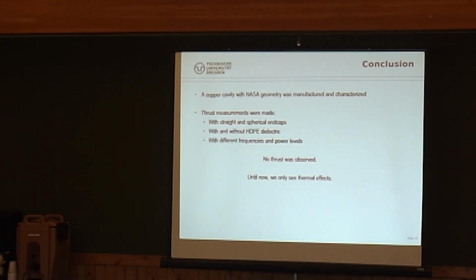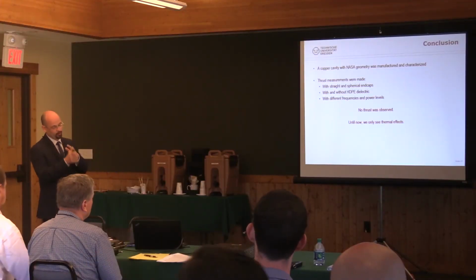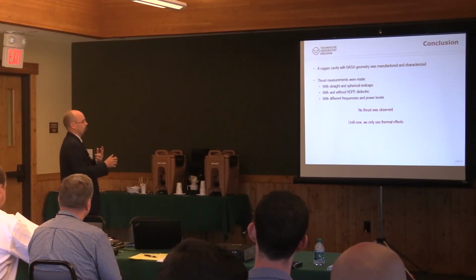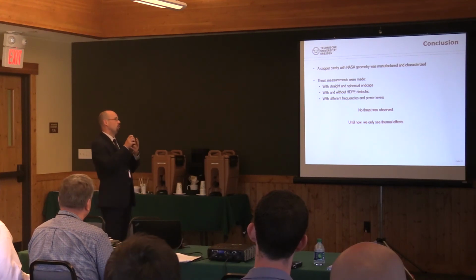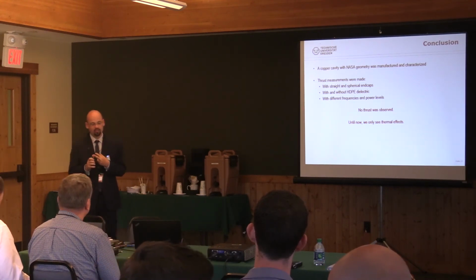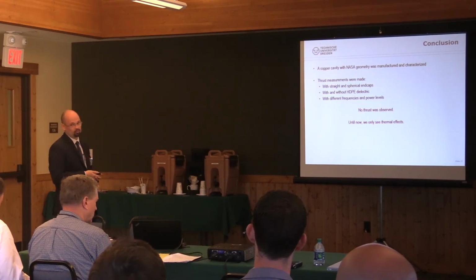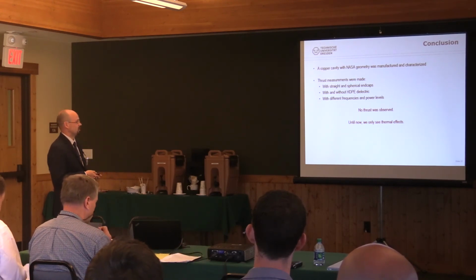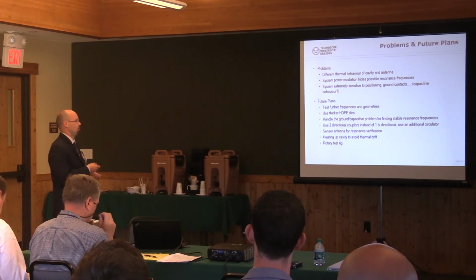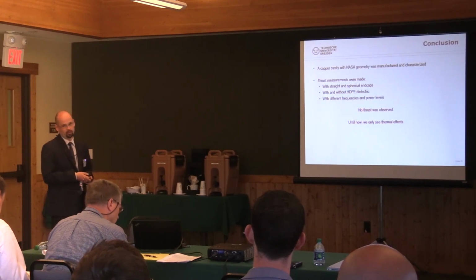Well, to summarize this, to conclude this, we manufactured and characterized a copper cavity after the design of another cavity. We used straight and spherical end caps, we used different frequencies, different power levels, we used high density polyethylene dielectrics and no dielectrics, and all we see until now is just thermal effects, and I'm afraid there's no thrust observed in our experiments.